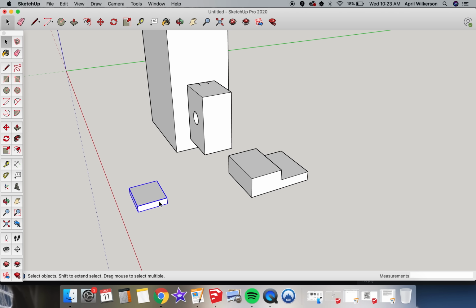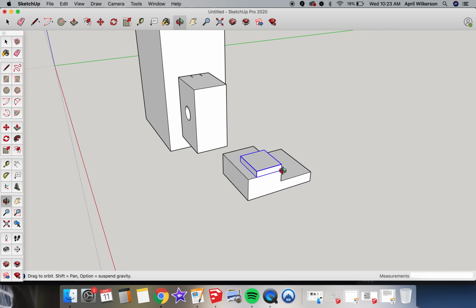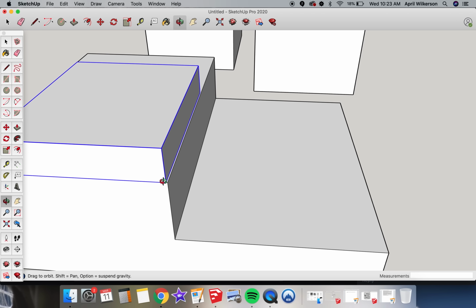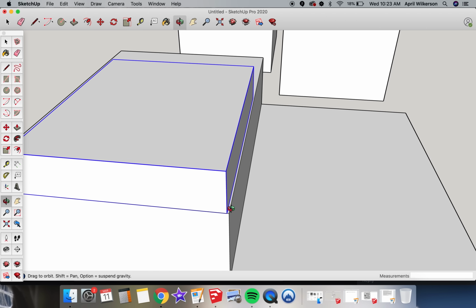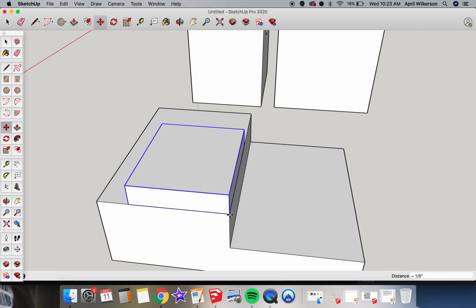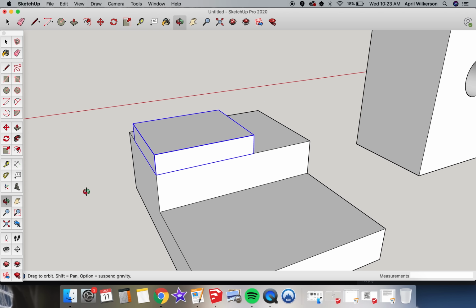It's very easy when you first start modeling to just pick up objects wherever. But to show you why that's a bad habit, let's pick this up by the front face and try to place the right corner flush with the right corner of the next box. It looks pretty good from this point, but when you zoom in and orbit around, you'll see that it's off. So to ensure things are flush and lined up, always grab things by a corner when moving in SketchUp. Pick up this corner and then click a second time on this corner to drop it. And now things are perfect.